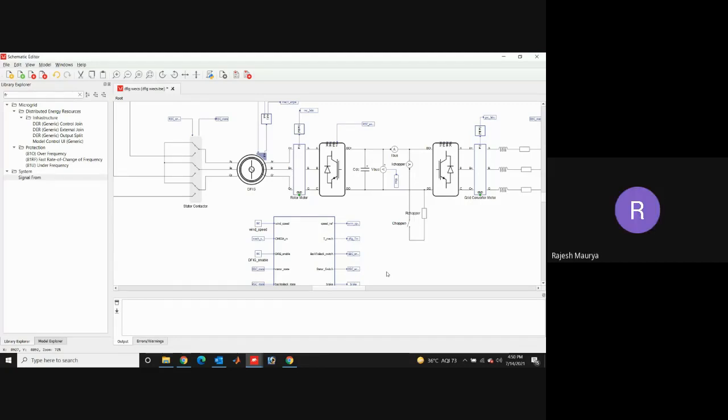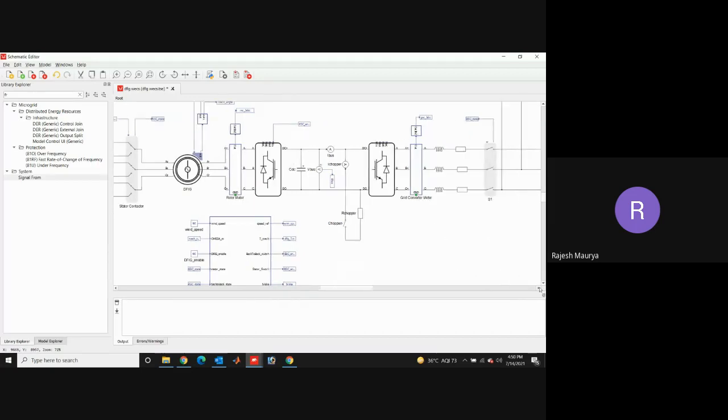Yes, sir. Okay. So now, similarly, we need to give signal to this converter and this contactor. So now it's done for RSC enable. For GSC enable, I'll copy this same From block. Already it's copied, so I'll just paste it over here, and I'm going to change its name to GSC instead of RSC enable, and connect with this. Let's check. Yes, it's matching. Similarly, I'm going to copy it from here and paste it over, to this enable command.